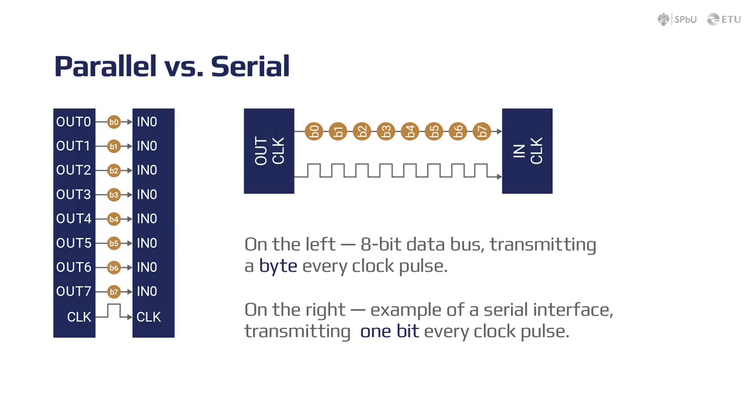consumption. What is the main difference between serial and parallel interfaces? Parallel interfaces transfer multiple bits at the same time. They usually require data buses, transmitting across 8, 16, or even more wires, so data is transferred in very large blocks. Serial interfaces stream their data one single bit at a time, only one. These interfaces can operate on a line with 1 or 4 wires.